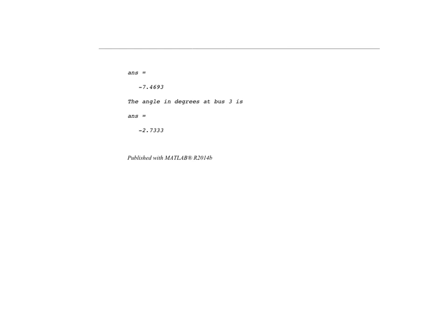Because that's it. As we talked about in lab, there's only 3 cases of bus, right? So you have a bus where you have 0 equations, or 0 unknowns, I should say, that you have to solve for. 1 or 2, right? Would you ever have 3? No, because the only thing you're solving for is V and theta.